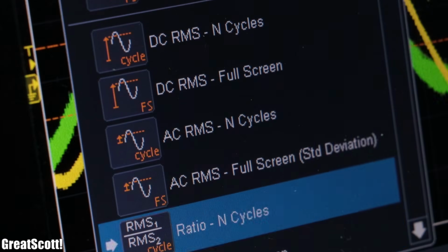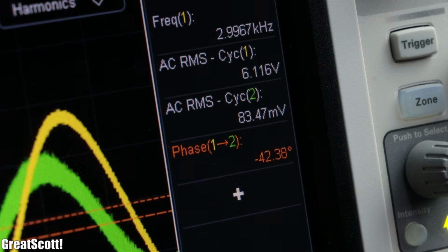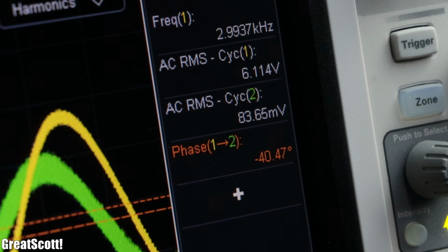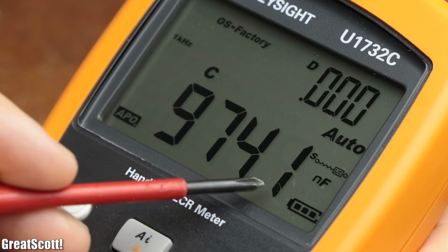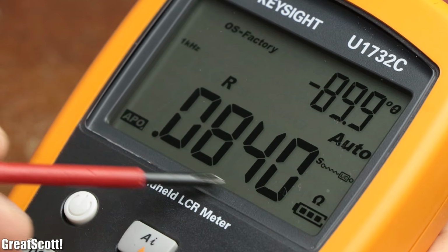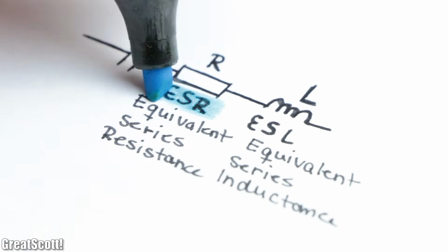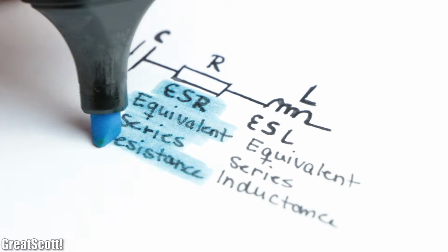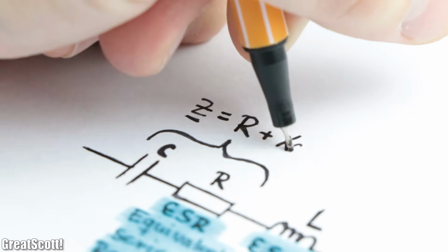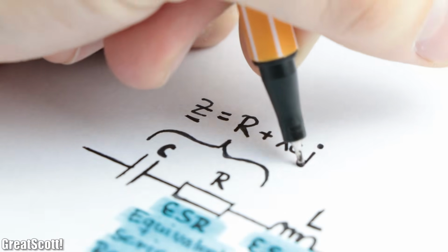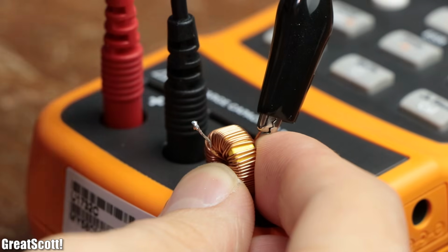By measuring the corresponding values at the practical circuits, we can see that our calculations were actually not too far off. They cannot be perfect, however, because our capacitor itself not only featured capacitance, but also a small resistance and even a super tiny inductance. Those values are known as equivalent series resistance and equivalent series inductance, and basically build up a complex impedance even without an additional resistor.